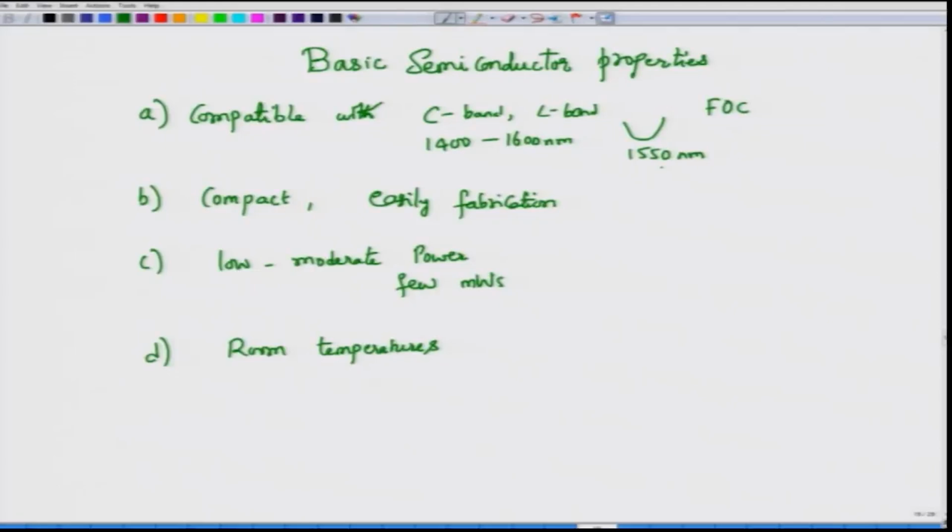Okay. And furthermore, it is just the right wavelength, where it is compatible with the fiber optic communication window or the telecom windows of operating an optical fiber, especially the C band operation. So, these basic properties of semiconductor lasers are very crucial in instituting this so called fiber optic revolution. The other ingredient of fiber optic revolution, of course, is the optical fiber itself.